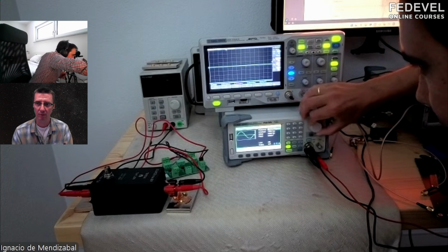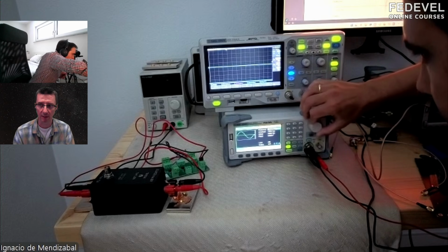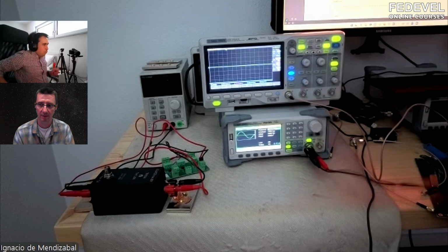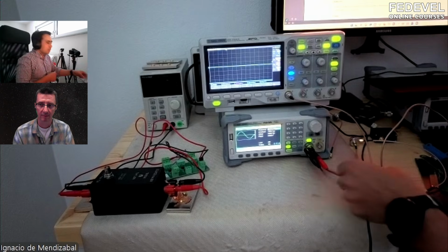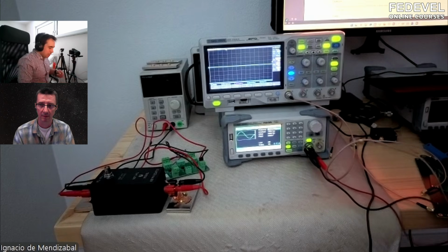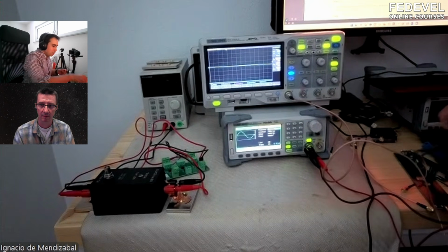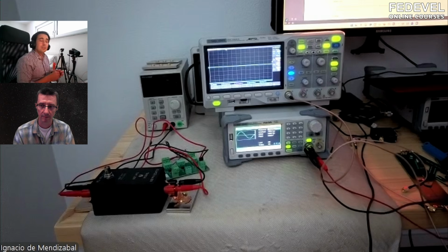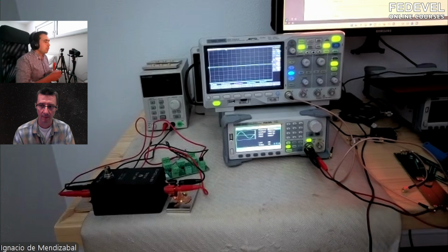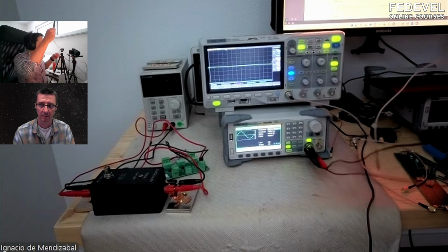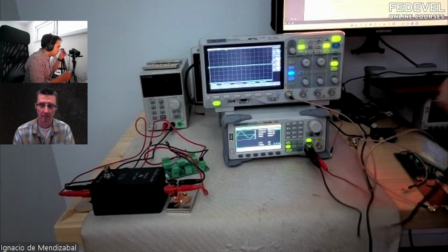And you say that you are using an oscilloscope, but are you using a spectrum analyzer function of a standard oscilloscope? For now, it's going to be just time domain, and there is a reason for that. In frequency, we are very used to seeing the signals in frequency, and we tend to forget the time aspect of the signals. I think it's important first, before moving to the frequency domain, to stay a little bit in the time domain to understand how probes work. And this is what we are trying to do today.